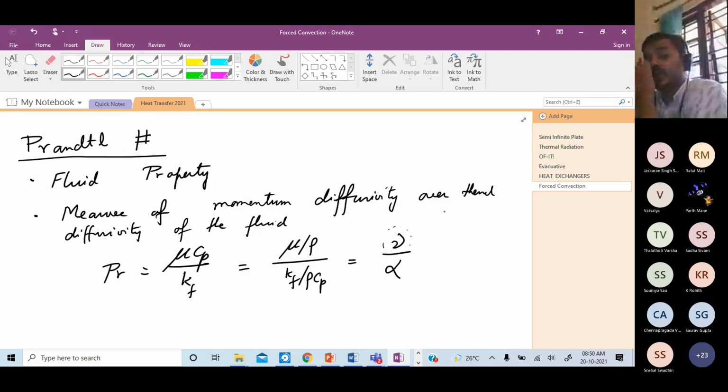Okay. Look, higher the viscosity, it means that the effect of the shear forces at the solid wall is going to be felt over a larger distance, right? Similarly, higher the thermal diffusivity, it means that the effect of this heated plate, which is suddenly introduced inside the fluid, is going to be felt over a larger volume of the fluid flowing over the plate.